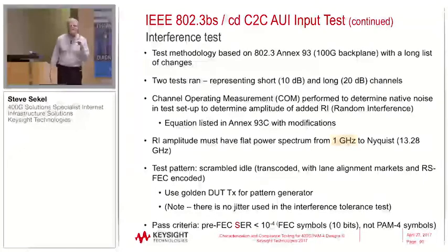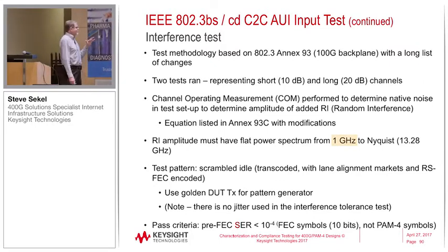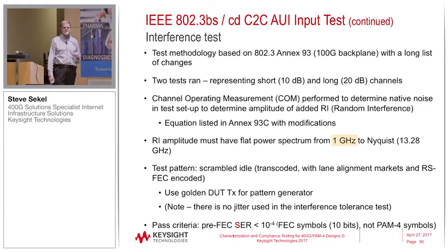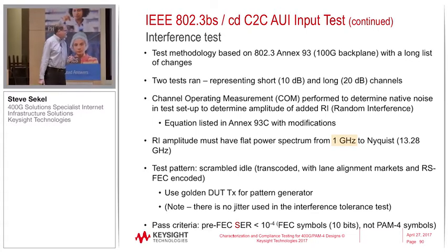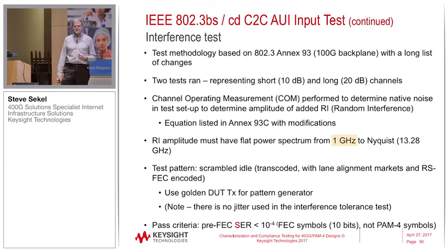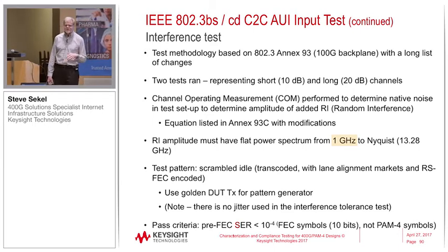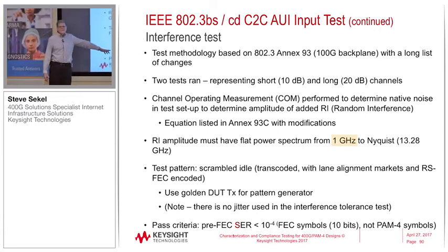Well, that's correct. You have multiple lanes. You have 8 lanes, okay, and you have to because it is striped, okay? So you would have essentially 8 separate test patterns, right? One for each lane. And yeah, the BERT can't do it because it requires too much hardware in the BERT to generate that. So how do you do it? Why did they pick this crazy test pattern? Because you already have this built into the SerDes.